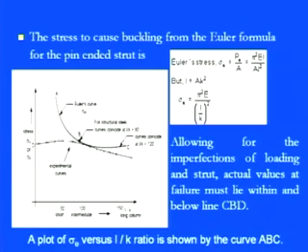So allowing for the imperfection of the loading and the strut, the actual value of failure must lie within the condition which the figure is showing here, where we have the Euler curve and the experimental curves. You can see that for a particular material, the structural steel, we have L by K of 80. The Euler curve and the experimental curve intersect at point B, for the specific case of structural steel where L by K is 80.